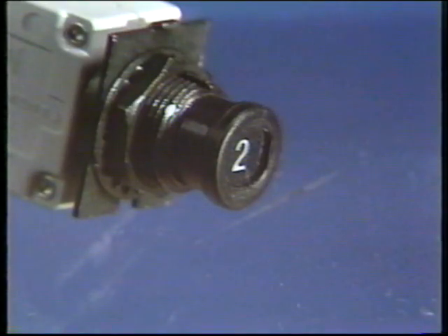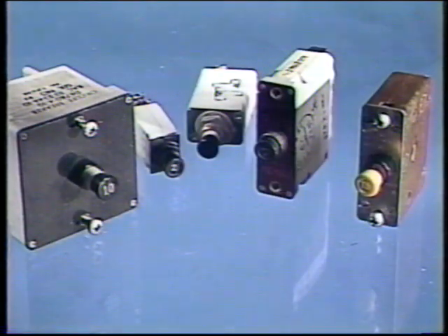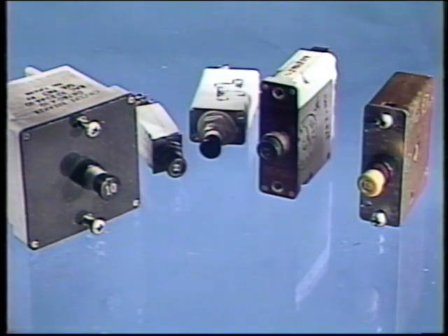If a fault caused the overload, the circuit breaker will normally break the circuit within a few seconds after it's reset. Aircraft circuit breakers are often of the trip-free type that will open a circuit if there is a fault, regardless of the position of the operating control. A trip-free circuit breaker cannot be reset until the fault is corrected.